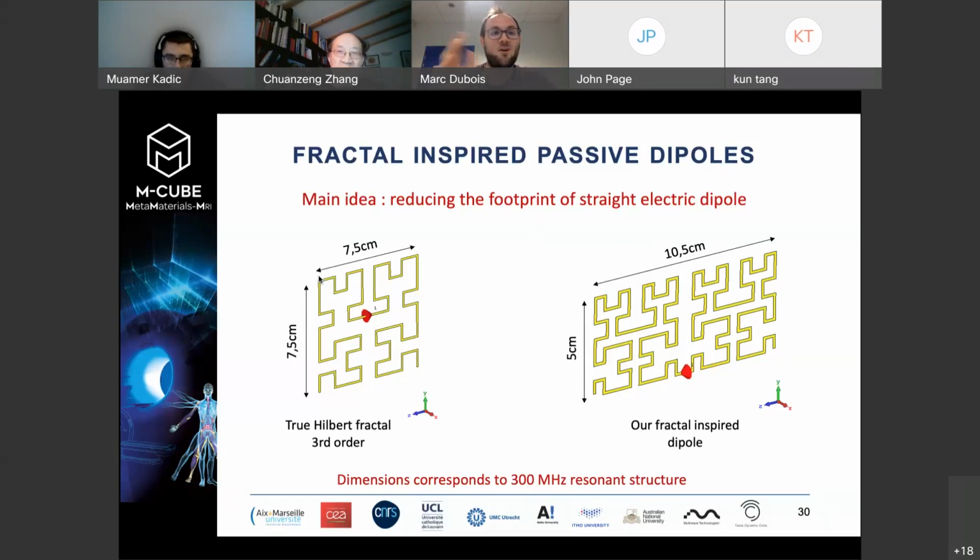So this is why I only show images at single frequency, and the structure is always at 300 megahertz, because in fact, the bandwidth that you need in MRI is just a few kilohertz around the central frequency that is in the hundreds of megahertz. So you don't really care about other frequency, only if you do single nuclei. As soon as you introduce more nuclei, then you have other parts of the spectrum to deal with.